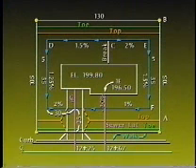After question 2, question 3 is a breeze. It asks for the slope from point A to the toe. We know the elevation of point F at the flow line of the swale from our work on question 2, and the fact that the top of the slope and point A are 1 foot above the flow line from the plan. We've already computed the back of walk elevation at the southeast property corner for question 1, so we know the